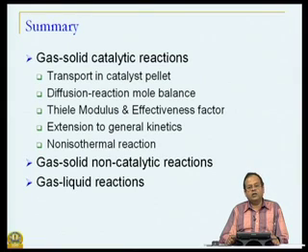We initially had this discussion based on an isothermal first order irreversible reaction in a catalyst pellet, but then one by one we went on extending this concept to general kinetics, to non-isothermal reactions, to different geometries, and saw there is some kind of uniqueness in the relationship between effectiveness factor and Thiele modulus.